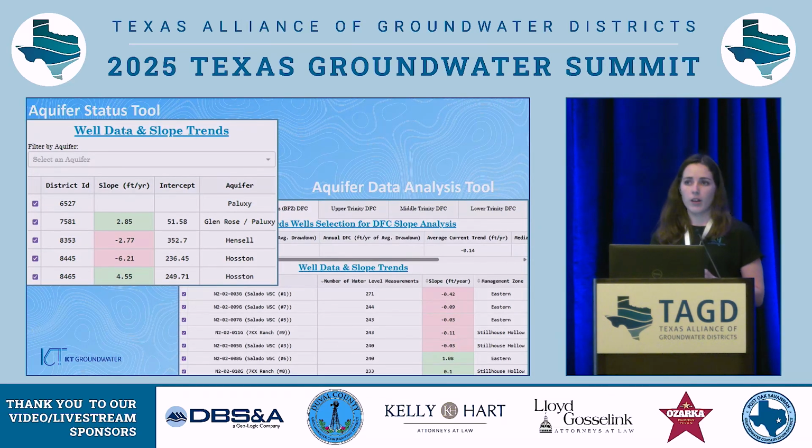So let's say that you have a monitor well, you know it has a hole in the casing, and there's water from a different formation pouring into the well. That's not a great situation, but it can happen, and this could artificially inflate the water levels, so you may not want that well included in your DFC trend calculations.